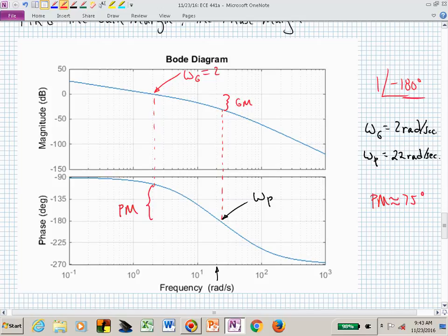What about your gain margin? How much can you increase the gain before you go to hitting 0 dB when you have your phase crossover? Again, you just have to eyeball it. And this is actually a linear curve or distance, isn't it? So now we're about 60% of the way maybe between 0 and 50 or -50. So we could increase this.